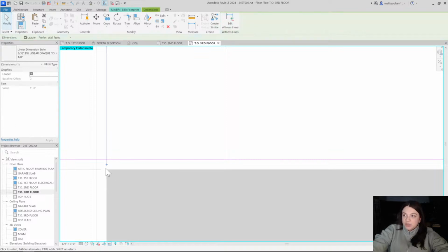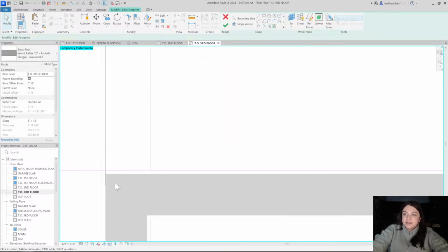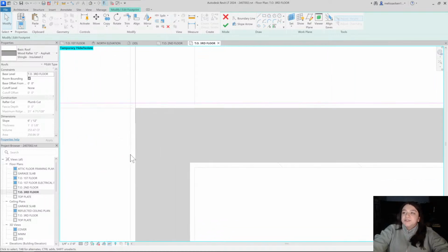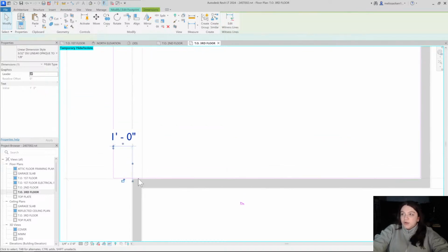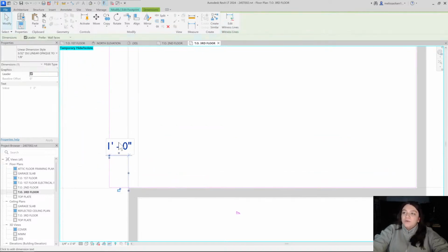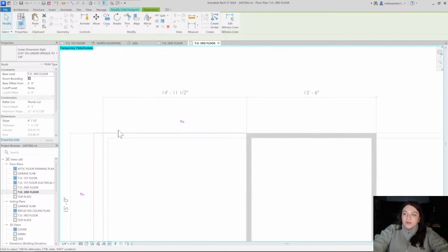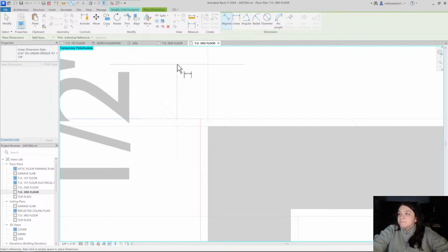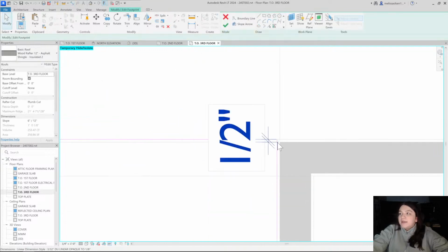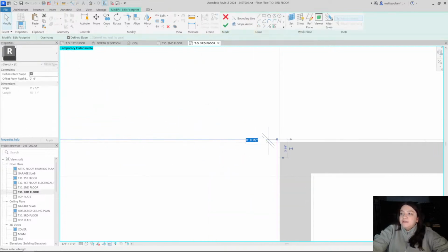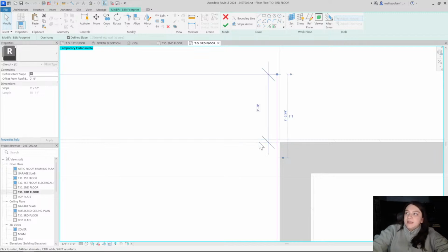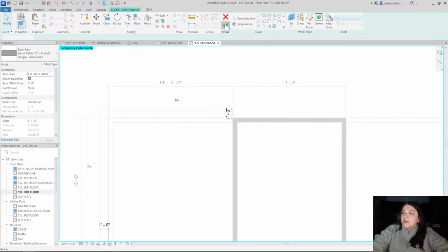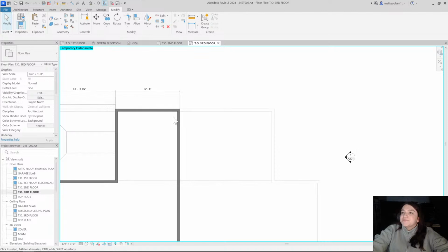That's our consistent point of reference in our entire project. Everything is based off that. This is just your outside layer that you add to. There'll be more than this, but I just draw the basic walls. So from that stud layer all the way out, you want your overhang to be 1 foot. And we're going to want that to happen on this side as well. So again, I'm marking that point and this point, and when I click on this line, it'll activate the dimension, and I can just type in the 1 foot mark. And then I'm going to hit OK.